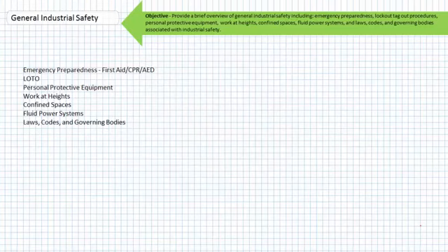Achieving a state of zero energy means that there is no source of hazardous energy present, nor can any build up during the course of a maintenance procedure. This is, again, not as simple as unplugging a system. Consider other forms of hazardous energy, including but not limited to thermal, hydraulic pressure, stored hydraulic pressure in an accumulator, stored electrical energy in batteries or components like capacitors, chemical energy, or suspended weights. All these forms of hazardous energy need to be locked out, blocked, or released.